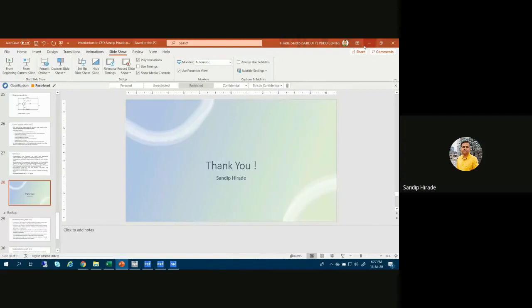In case of unstructured hexahedral mesh, now we are using hexahedral, but in case of tetrahedral, the quality will be very low, like 0.1 or 0.2. So in tetrahedral, try to achieve a quality more than 0.2. That means it depends on the meshing also, whether it is tetrahedral or hexahedral. It depends on the type of problem, whether we are going to use tetrahedral mesh or hexahedral mesh.